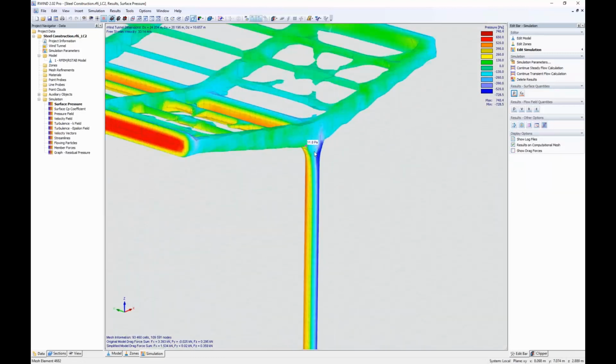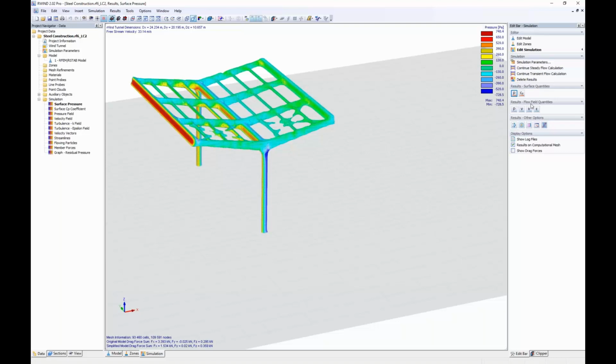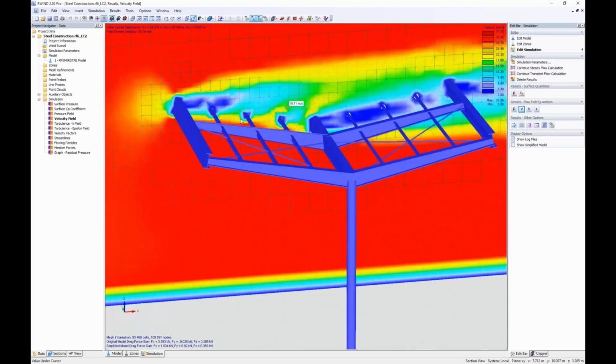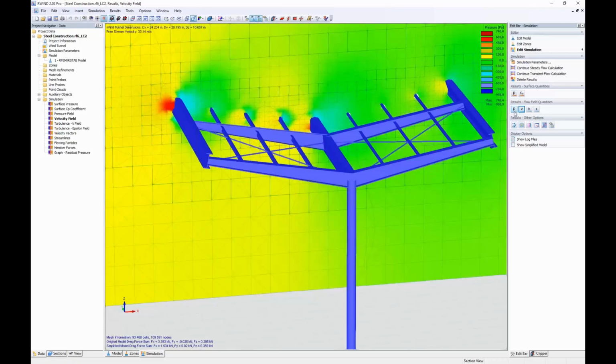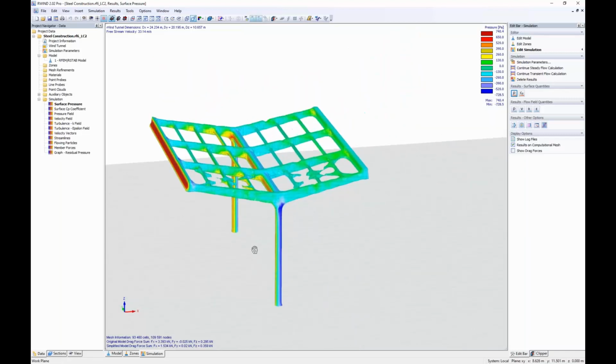Yeah, the program makes it windproof by binding a foil around and calculating the wind flow around, let's say, this model, and creating from this wind flow around pressures, or it's a result of this flow around, and creates from these pressures a pressure skin on this model. And these results will be used in RFEM for calculating the structure itself with the wind loads. But what you see now, and this was my target.